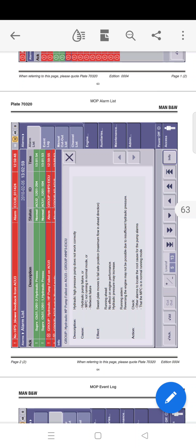Now what do you mean by ACK? Acknowledge. This is the acknowledgement status field of the alarms, containing an icon toggling between the two states, alerting the operator of a non-acknowledged alarm. In red color with the exclamation sign, it is a non-acknowledged alarm in alarm state. If the exclamation sign is green, it is a non-acknowledged alarm in normal state. And if there is a sandwich symbol in yellow color, it is a non-acknowledged alarm in alarm state waiting to be acknowledged. So these are the states.